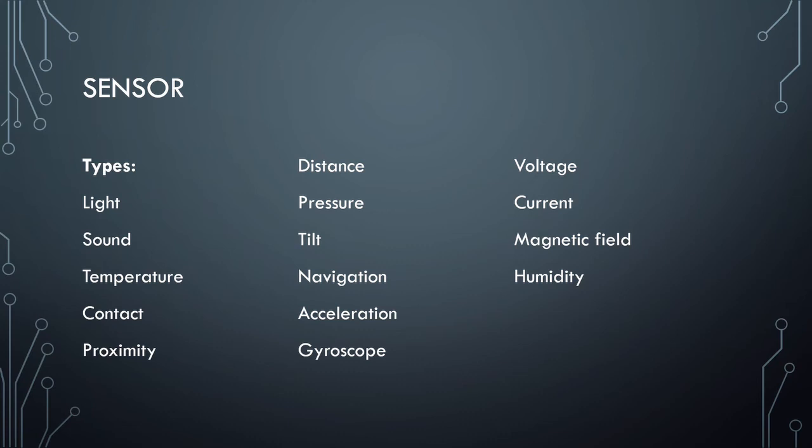So the acceleration sensor can tell the controller how quickly the robot is accelerating. It can see if it's meeting what it needs to. A temperature sensor may indicate the need to adjust the program for certain things based on the temperature. For example, we talked about the drive systems being sensitive to temperature, so potentially you could program to compensate for that. If there was pressure applied to the robot, it could be programmed to stop moving potentially, so it's not knocking into anyone or anything.